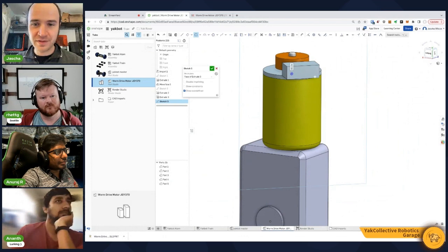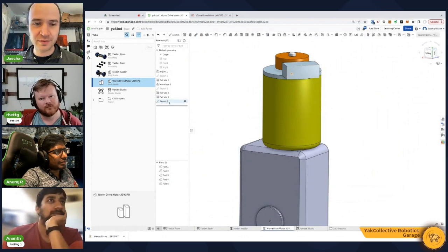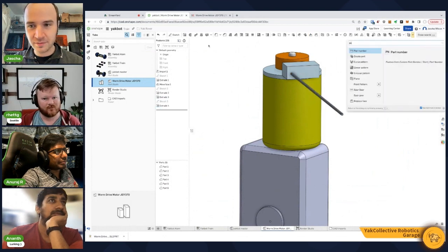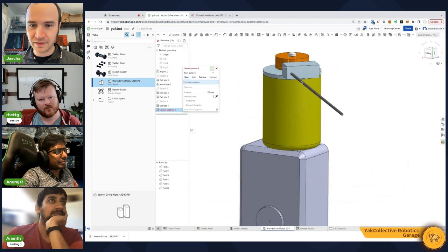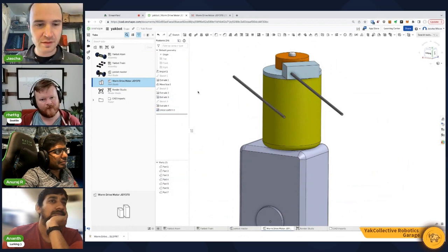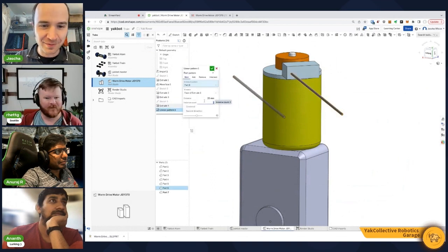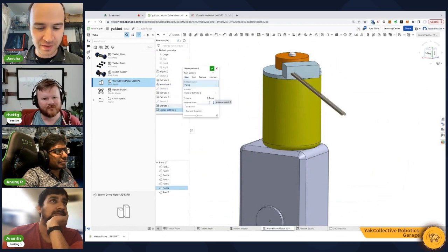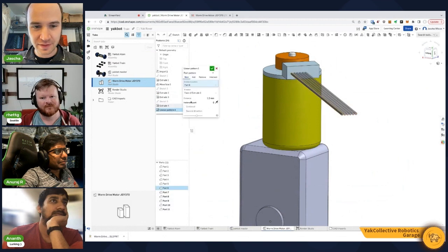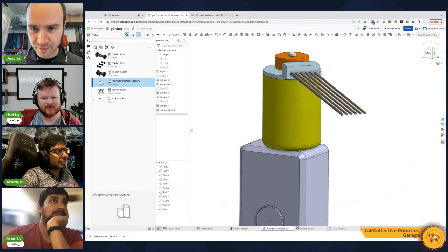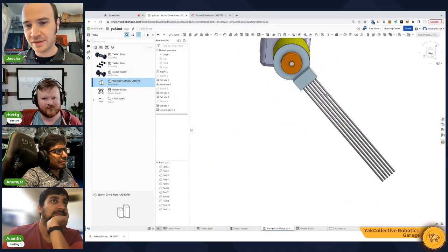That's a whole thing. So for instance, if we do add a wire into this model, just for giggles, we do this, and then we make a pattern. I take this and make, this particular product has 6 conductors. That's not 25 millimeters. We want like a 1.2 mm spacing. We want to flip the direction and we want 6. Okay. Actually, the spacing is much higher. Oh, I think it's a 2 millimeter pitch. Yeah. Okay. So, you know, we can add this in there.